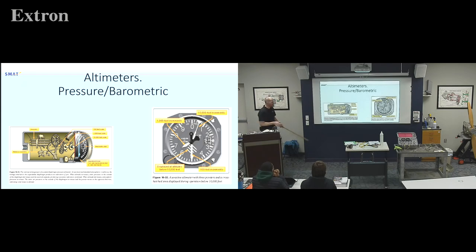So, the hands on an altimeter, there are many hands here. We've got a 100-foot increment, so that one's pointed at the 5, so that's 500. And then we've got a 1,000-foot increment here, kind of like the hands on a clock. The smaller one is the bigger number. I don't know why they do it that way. It seems like it should be the other way around. Probably because we're more focused on this one. So right now this one's at 6,500 feet indicated.